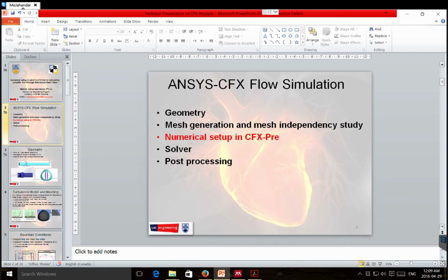On this step, you should avoid any kind of sharp edges on the geometry or any small surfaces or small volumes in order to prevent mesh concentrations around these regions.